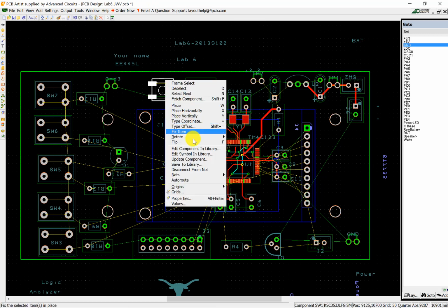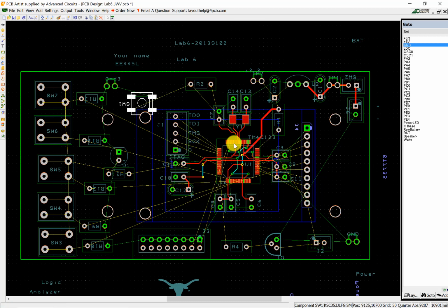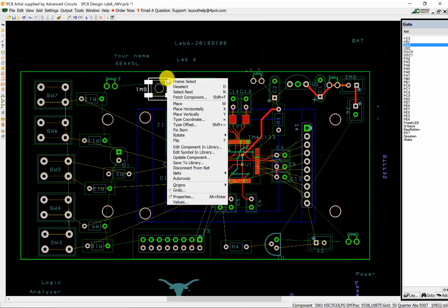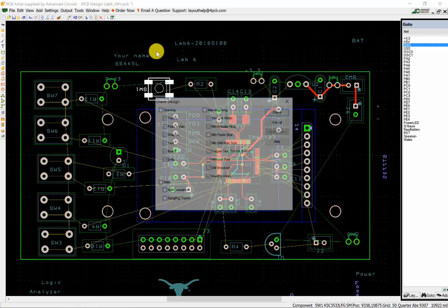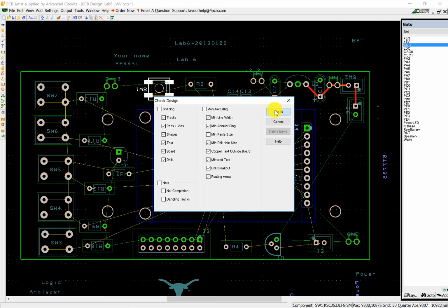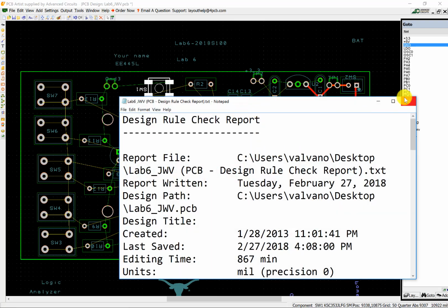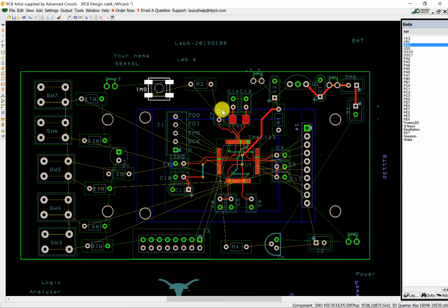this guy at around 180, again, I'll do a design rule check here to get the nets to come out. All right, that didn't actually make it better, did it? That made it worse. Ground. Oh, that's okay. All right, so now I'm going to tie all the grounds together.